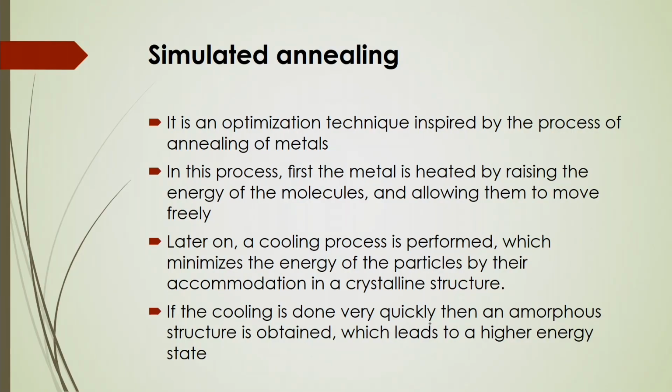It is based on how metal is heated by raising the energy of the molecules and allowing them to move freely, and on the cooling process, which minimizes the energy of the particles by their accommodation in a crystalline structure, and also how quickly cooling then gives an amorphous structure, which leads to a higher energy state.